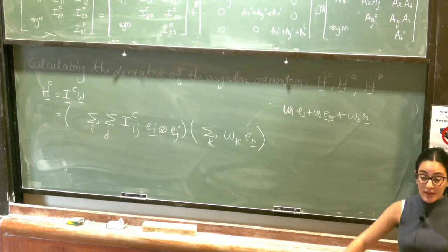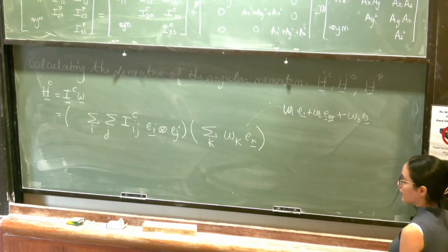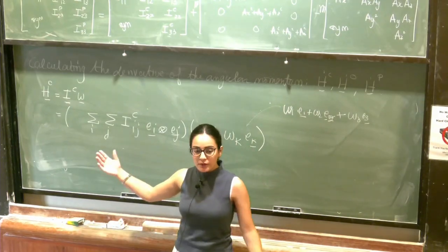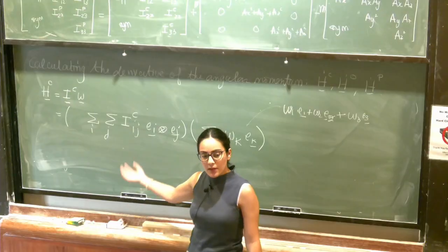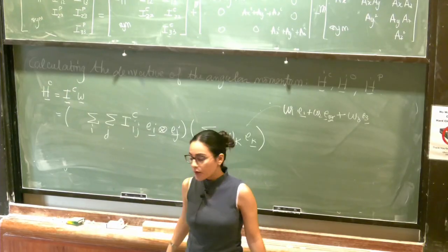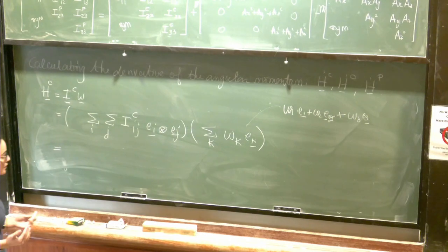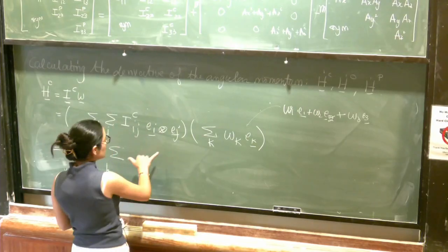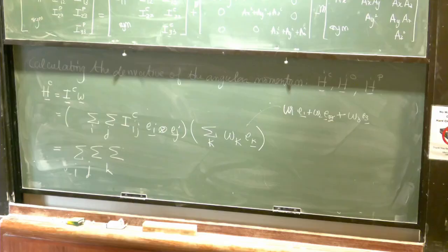So these developments are general for the angular velocity being any vector in 3D. And this is another notation for the tensor: I11 e1 bond e1 plus I12 e1 bond e2 plus and so on, 9 terms. So I can take all of the sums to one side, i, j, k, and now each tensor is applying to each vector here. What was the definition of the bond product?